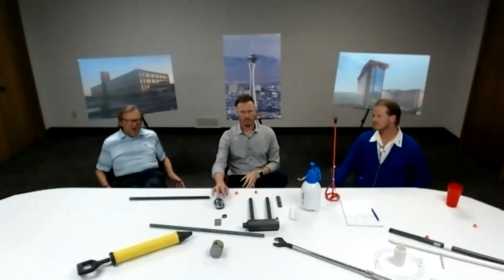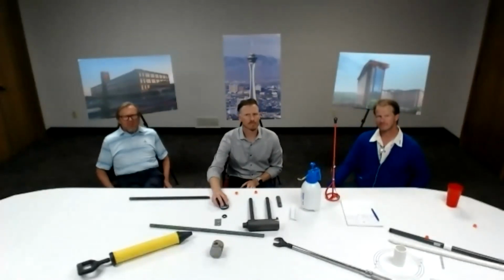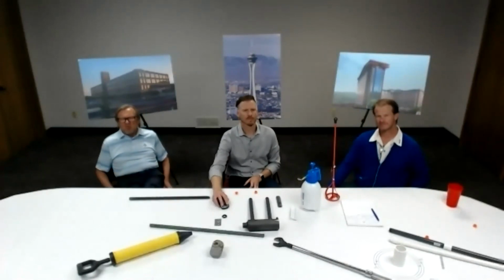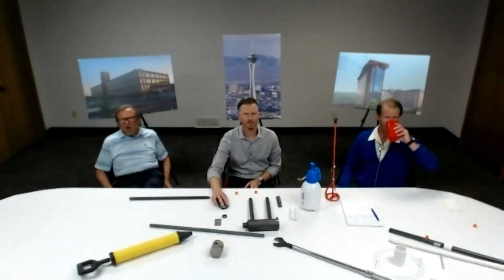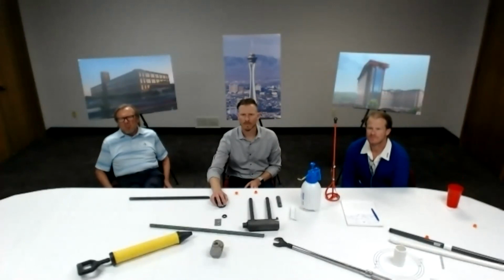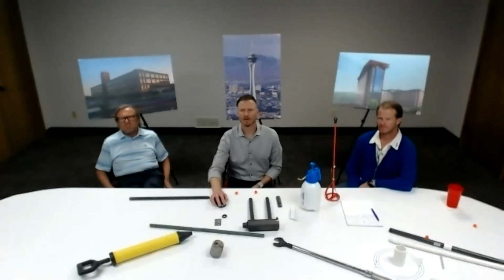One of our goals here is to take pressure off the EOR, because normally it isn't getting in the general's way not to grout them. Even if there's a few shore posts, mega shores or whatever, 8 feet apart downstairs or 12 feet apart, this really doesn't interrupt his construction very much. So the pressure would be off. But if someone wants 28 days, 20 days, that's an EOR call on when you would pour back a pour strip.